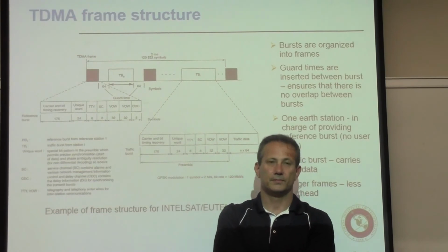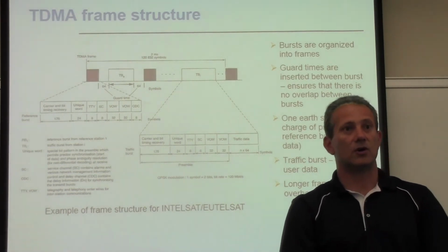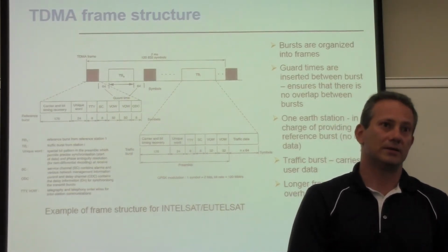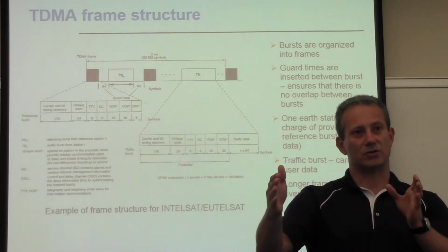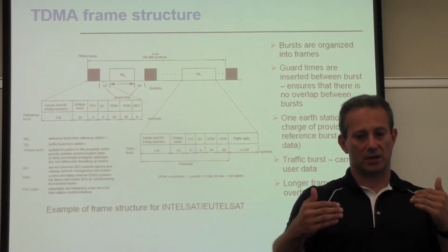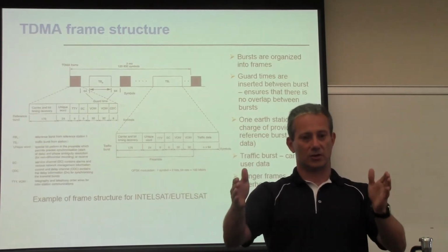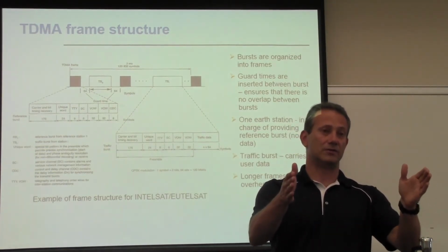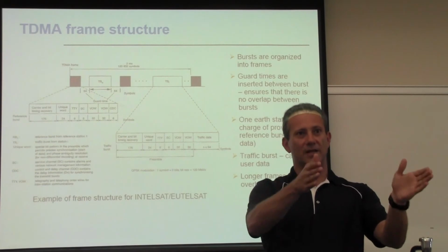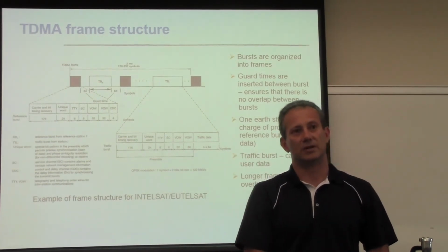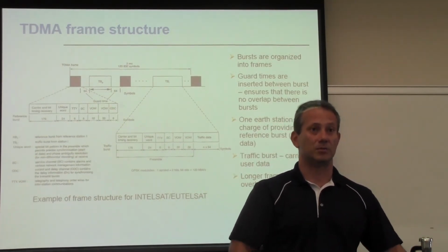So how often are these short bursts sent? Hopefully they're sent only when you're acquiring, right? Because you're not drifting all of a sudden, you drift slowly. As you keep on receiving signal, you say, okay, this drifted, and that's why you have these guard periods. Your signal starts drifting, and then you say, there is a drift of so much, so advance it. So you're always wobbling and then issuing commands that advance transmission to stay within a given frame. You never allow it to drift outside of the guard period, because that would be excessive.